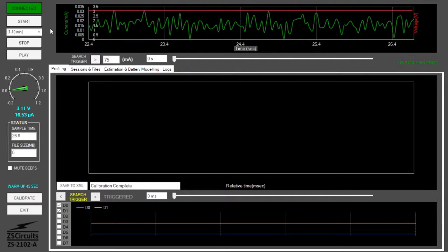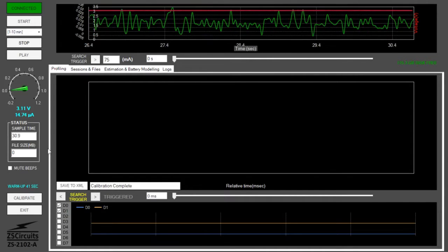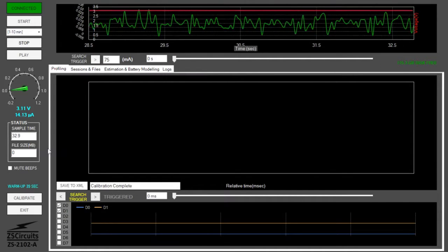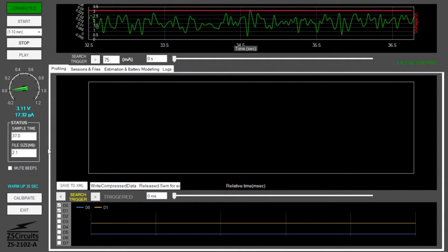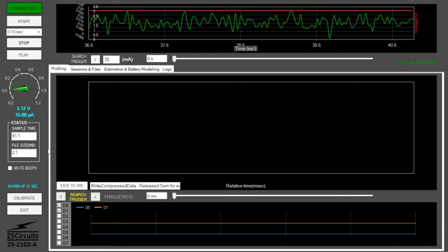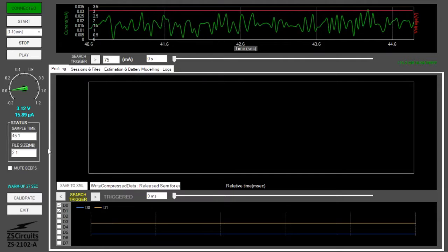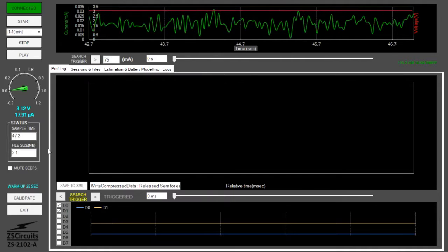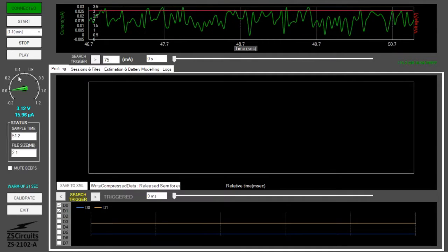It continuously samples the current and voltage to provide an accurate estimate of the power consumption. The tool sends about 64 megabits of data per second over the USB bus to the GUI software. Using state-of-the-art compression method, the final bit rate is reduced by almost 100x. Storing compressed data allows the tool to record profiles longer than 10 hours at a stretch.